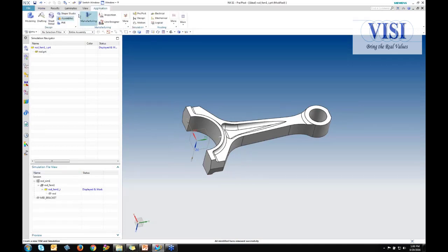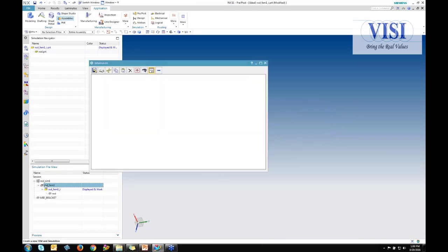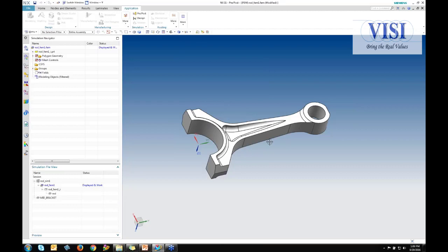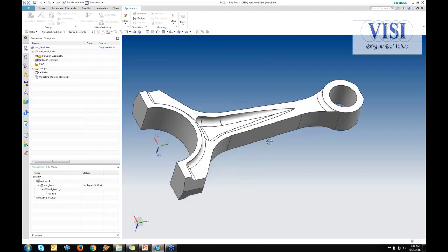But if I wanted to, I could always step out of this application and move right into modeling. And once I get into modeling, I'll have the full suite of NX to make these changes. But for this example, we're just going to do something as simple as removing those blends. Those holes, I'm sorry. So let's go ahead and step up to the fem model. Just let me know that I made a change. And let's go ahead and mesh the part.